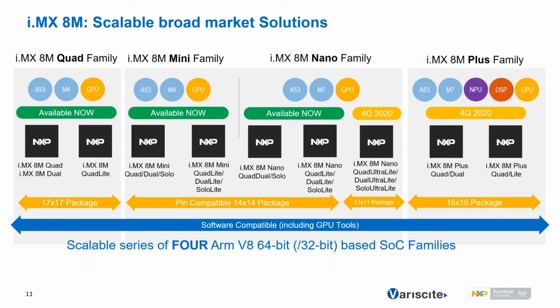If you look at the 8M series, which was the first part of the i.MX 8 family to launch, the 8M series consists of 3 families that are launched and one, the 8M Plus, that will launch at the end of 2020. The 8M Quad launched in 2017 and was the first i.MX part specifically aimed at the multimedia market, supporting 4K HDR, HD audio, which maintains the overall family approach because we have pin-to-pin compatibility across the different variants of that